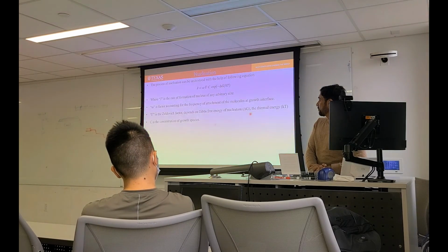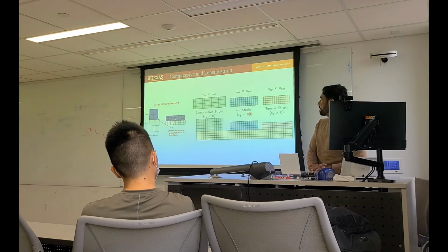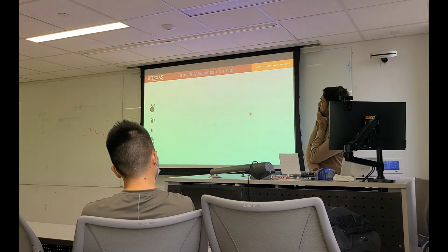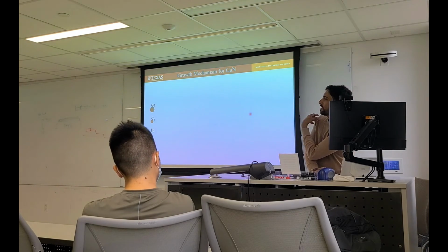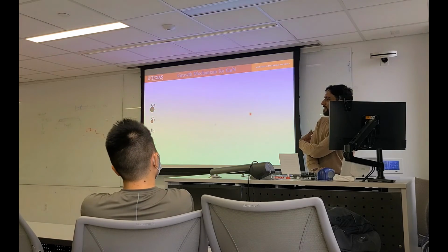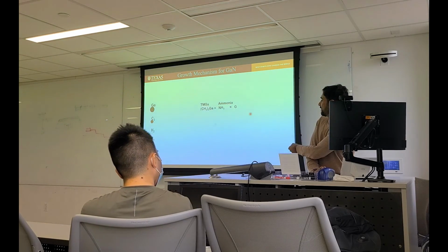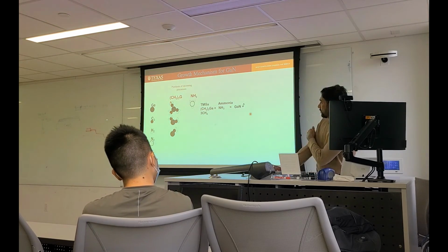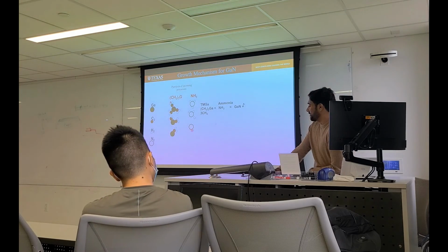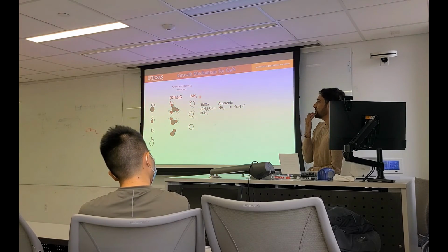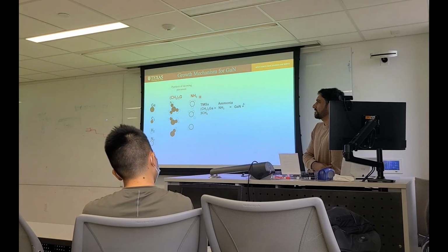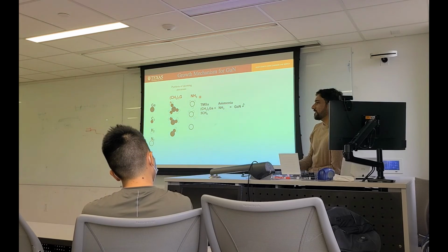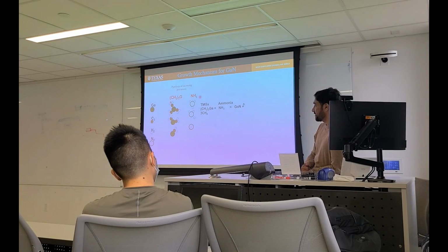Okay, so I just move to my last slide. I just added this for gallium nitride because I talked about gallium oxide. I'm supposed to work on gallium oxide, but my experience is actually on gallium nitride. So this is an NH3 source. The dissociation temperature for ammonia is around 600 degrees centigrade. So you can break it and make very active nitrogen radicals from NH3 from 600 degrees centigrade.